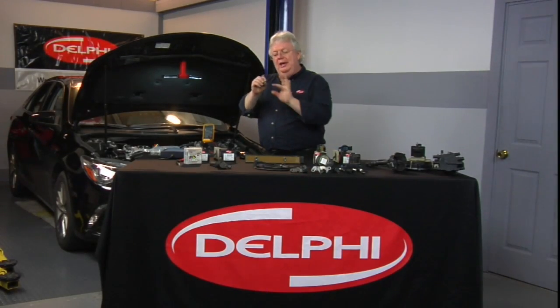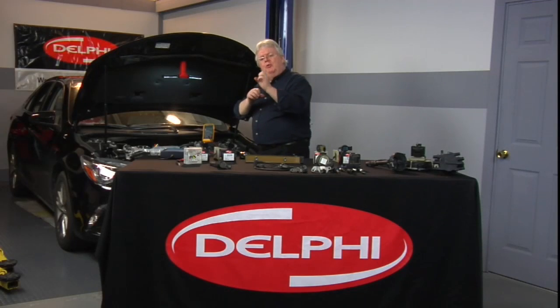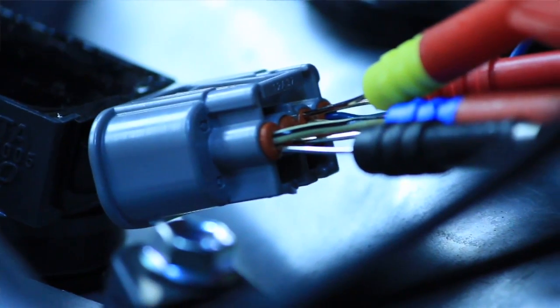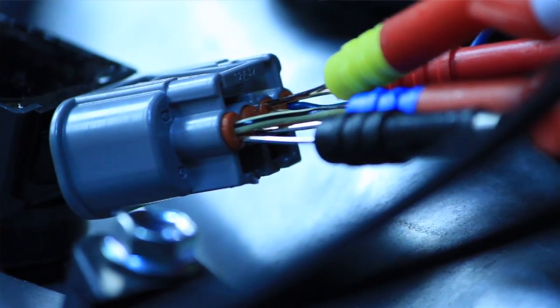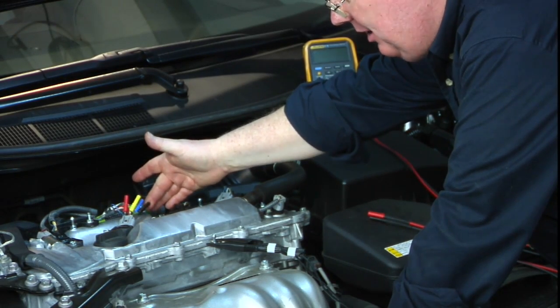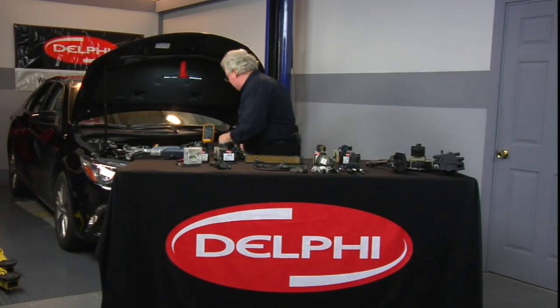So we're going to use these little AES wave back probes here and slide between the terminal and the rubber insulation that covers and seals the terminal, and actually back probe it, butt it up against the metal terminal of the wire itself, which we have here. So red is our power from ignition, black is our ground. That's just so this coil-on-plug module can wake up and start working.